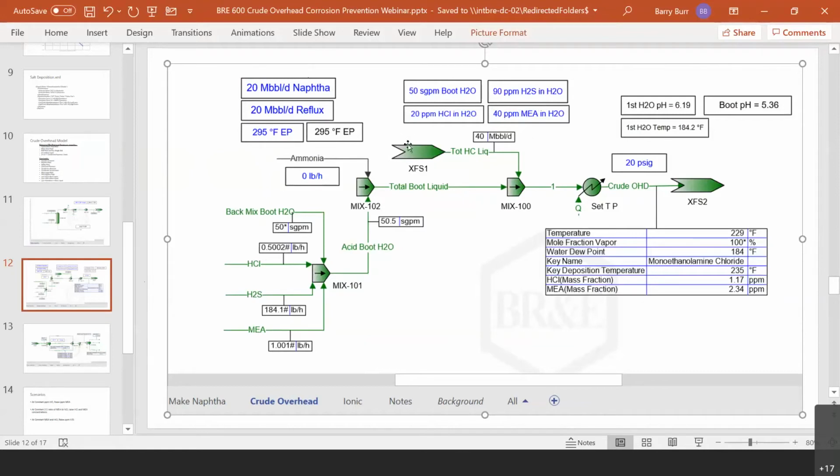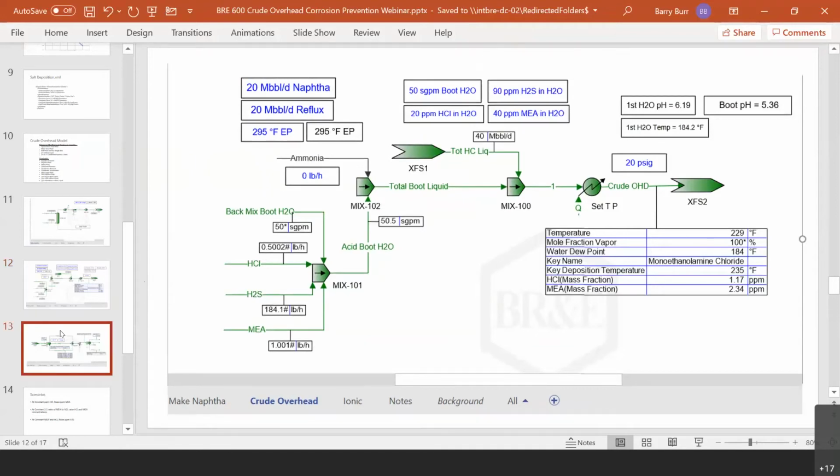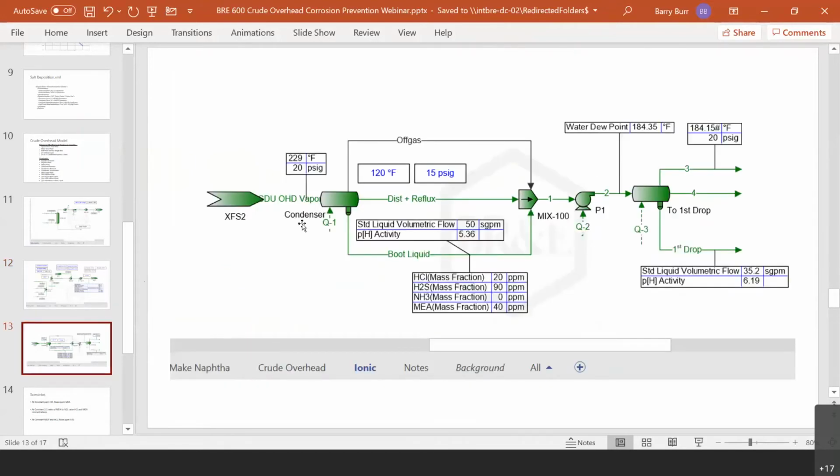That's what you would need to provide on this flow sheet. This is all done using Peng-Robinson, so there's no ionic or electrolytic thermodynamic calculations involved. However, we do transition to another flow sheet which does use an electrolytic package, and we need to do that because we need to calculate the 3-phase electrolytic flash in the condenser, and also towards the right we replicate this,